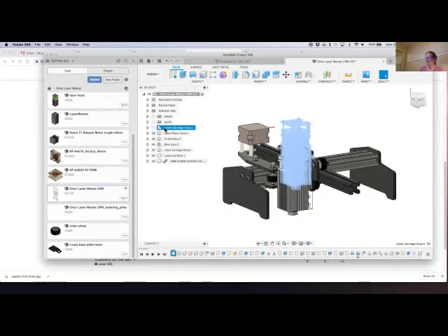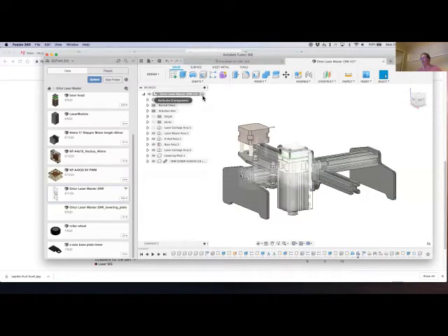Now this is a little confusing here because I actually replicated the laser carriage assembly. I should be highlighting this one. And that brings up another point though. If you have a reason to have multiple sub-assemblies in an assembly, then part of your organization of what goes in that sub-assembly is probably going to be all the things that you want to replicate when you replicate the assembly. You might have 2, 3, 4, or 5 of the same sub-assembly within an assembly, depending on what your product is. And where this gets tricky is you need to keep in mind what you're working on.